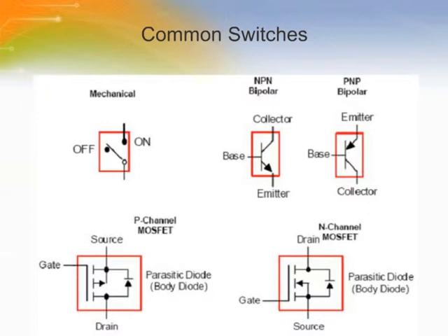In the electronic switch category, semiconductor devices are made up of NPN and PNP bipolar transistors, as well as N and P channel field effect transistors, or simply FETs. When a FET structure is used in an IC, it is more descriptively referred to as a metal oxide silicon field effect transistor, or more simply a MOSFET. MOSFET switch structures are used in very large numbers in ICs and bipolar transistors to a lesser extent.